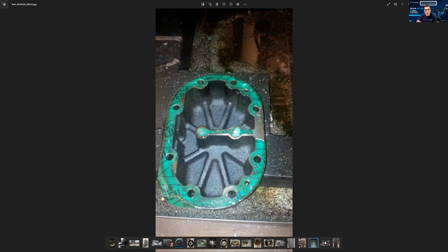If it's a semi-hermetic or a hermetic and it's not running, you can't get it started, make sure that there's no special device inside that hermetic compressor that's keeping it off, because I've seen this time and time again. It could be the internal protector off. It could be sensors in the windings that's keeping it off. It could be an ASTP. There's lots of different things that could be keeping it off. It could be a drive that's keeping it off. It's on a variable speed application, and you think the compressor has the issue.